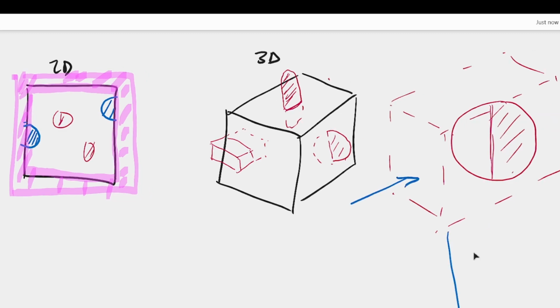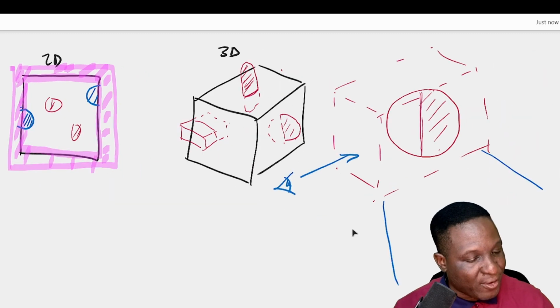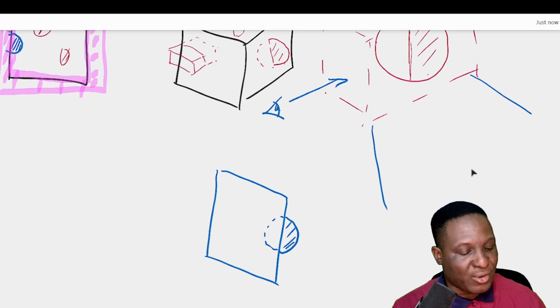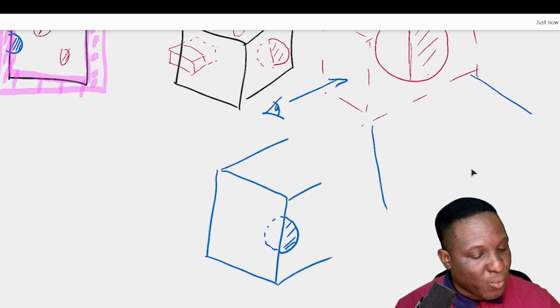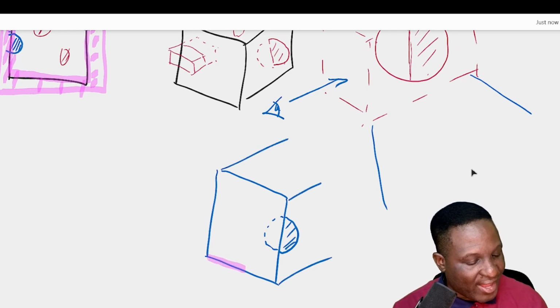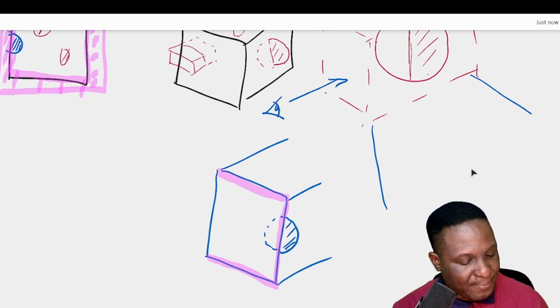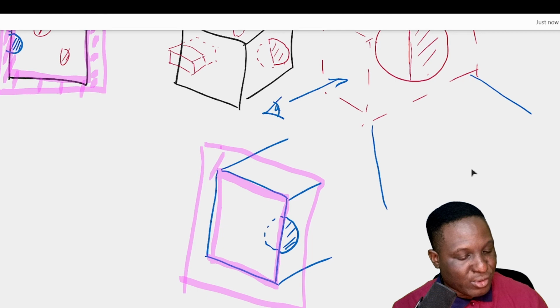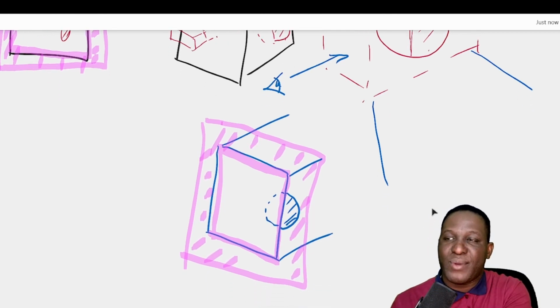If we watch the system from this angle, what we will see on the side view here would be a system that looks like this. So there will be the particle that is being seen on the corner. That's clearly what we want. So what we then need to do is to find a way of isolating this system again, and then we'll find a bigger system around it that we're going to use to extrude cut, just like we did before, so that it trims off what we're looking at.